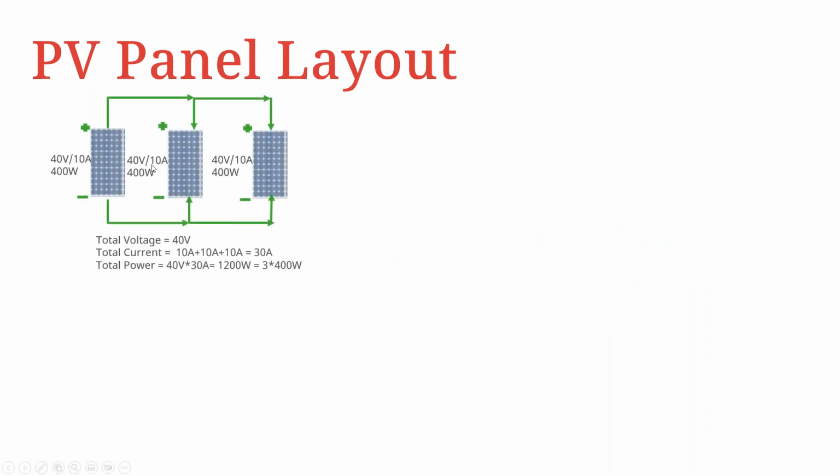First off is a power connection with the same specifications as before, but in this case, we have a parallel connection. For all parallel connections, the voltage drop is the same. So in this case, we're going to have 40 volts as the total voltage. But in terms of the total current, it's going to be a summation of the current flow through the respective panels, because the current that flows through this panel is different from the current that flows through this panel, if they have different specifications. So basically, to get the total current, the currents through the branches have to add up.